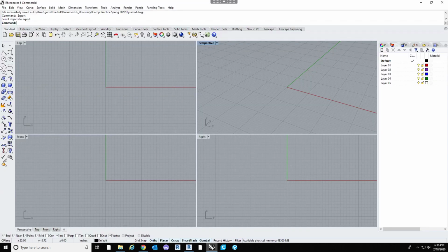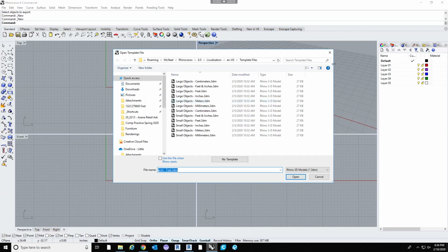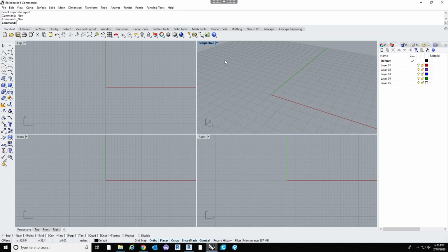So open up Rhino. It doesn't matter what geometry I have units. I have inches right now. You can do feet, and you can do other units, but imperial is the easiest way to go since that's what Revit reads. And all we'll be doing is just creating a really simple geometry. So down under the solids tool, let's do pyramid. Let's do the center.